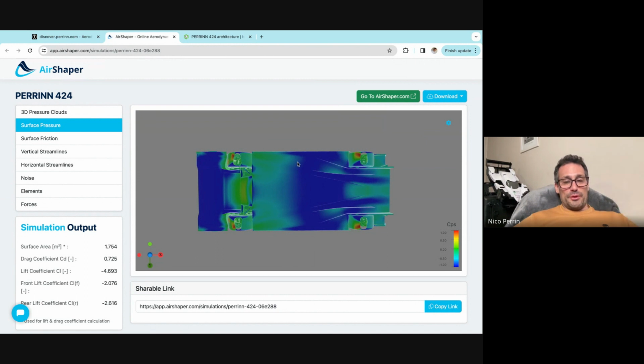In the modern Formula One cars, the whole floor now is a diffuser, so the kick is at the front of the floor, and the whole floor is curved. Versus the previous generation of Formula One cars, where the kick was actually at the rear axle or just in front, and most of the floor was flat.